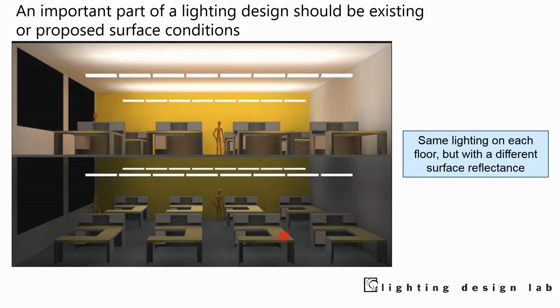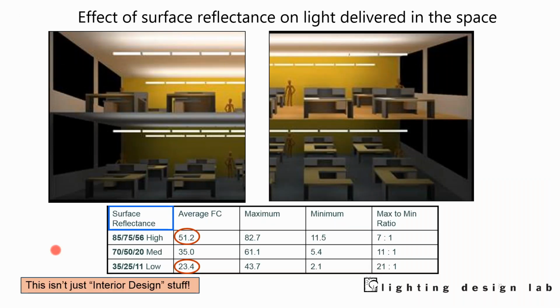So if you ever do lighting calculations, you have to tell the computer model about the space. You have to define the size of the space, the volume, and then you have to tell reflectances. And if you don't know the reflectances, there are certain default reflectances. So we assume 70% for the ceiling, 50% for the walls, and 20% for the floor. And those are industry standards, and it usually just defaults to that because that's often what you will find in many spaces.